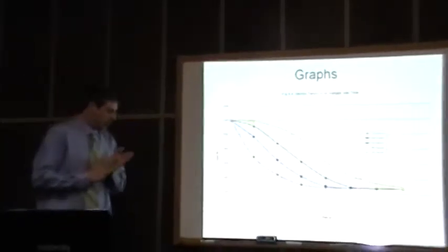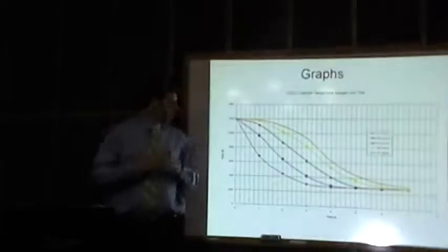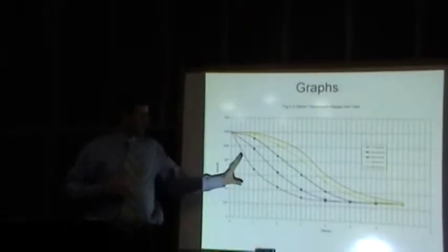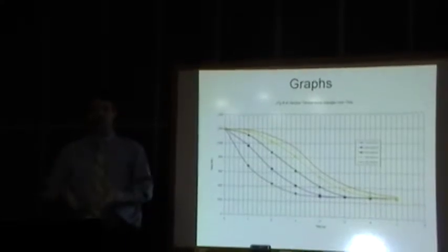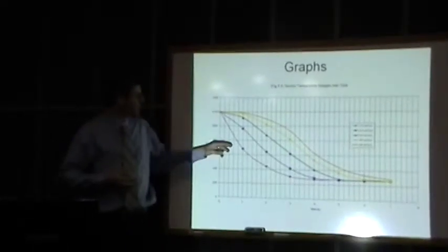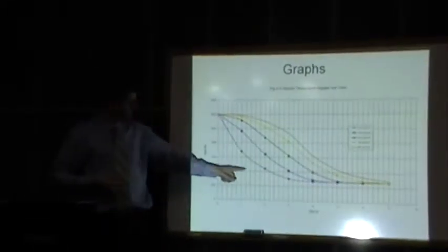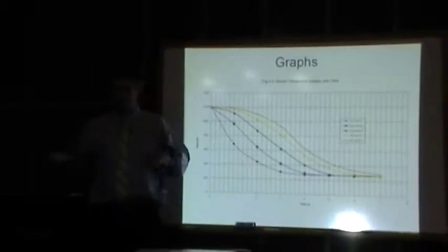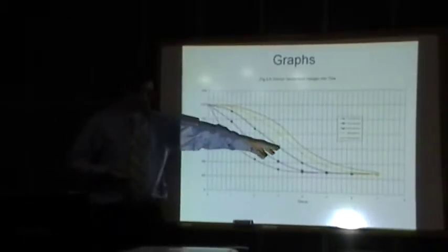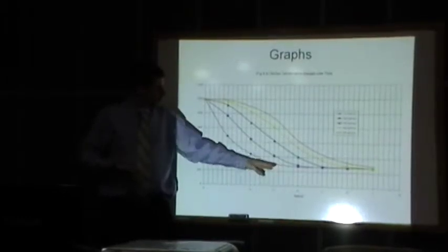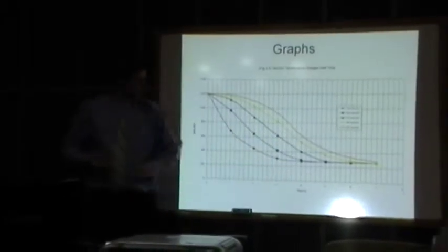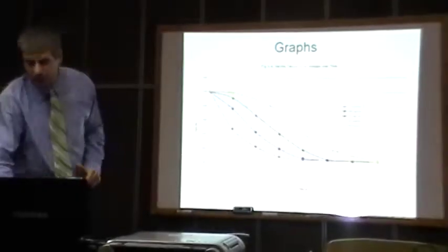Here are the axial conduction curves, which is the last calculation I did to try and model conductive heat transfer through the beryllium core. If we look at the first section, it cools off very rapidly as would be expected, and the other sections cool off slower than the first section, but by 7 seconds they're all pretty much cold.